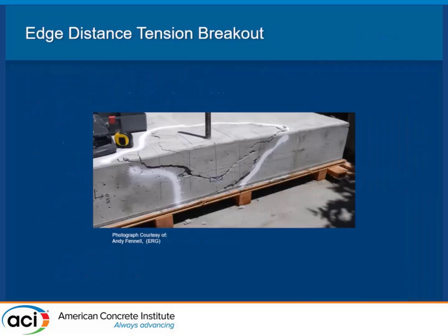All right, so let's just move ahead here. Then that's out for where we've got concrete in tension out in the middle as we get close to an edge. You can see as well, boy, this 35 degrees just keeps popping up. And of course we have equations that adjust for the concrete breakout, and you would have to know how close you are to the edge and all that kind of stuff, and the code tells you how to do all that.